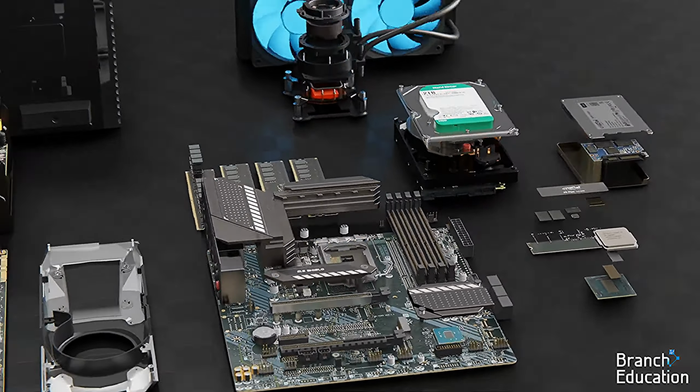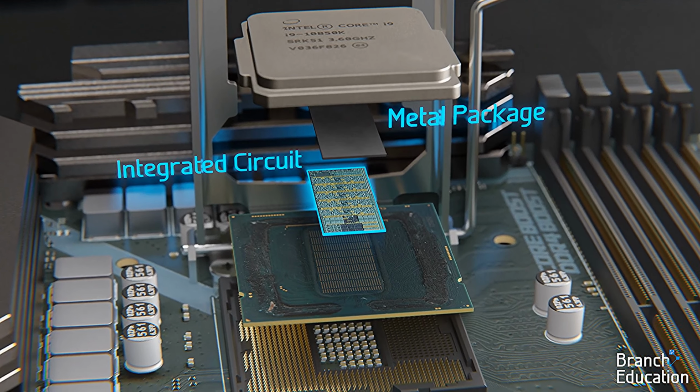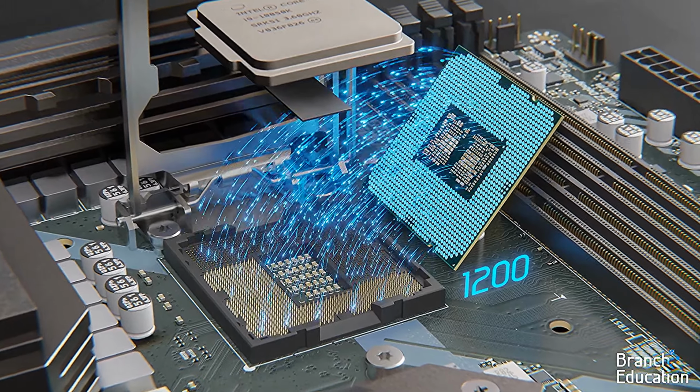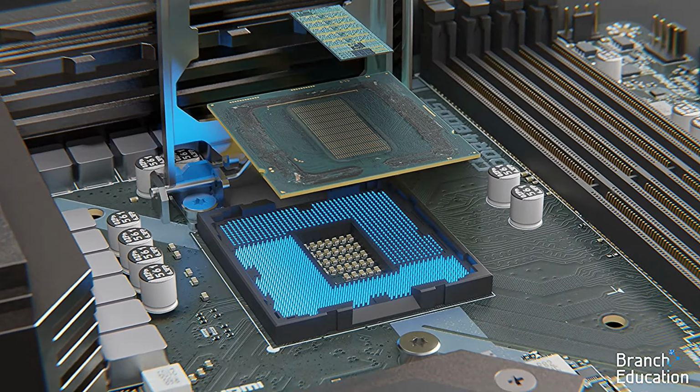We'll begin this journey with the Central Processing Unit, or CPU, which is the brain of the computer. On top, we have the cover, called an integrated heat spreader, and inside is a smaller metal package that holds the integrated circuit, which is technically called a die. This die is mounted on a printed circuit board that distributes the 1200 connection points to landing pads that interface with the land grid array on the motherboard.